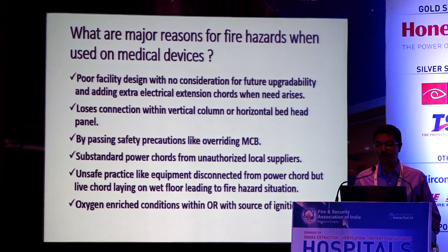The horizontal bedhead panels and vertical columns need to be maintained also. But people don't care for those things, although they are being used heavily. So we need to have a maintenance schedule for those things. Bypassing the safety precautions, like overriding the MCBs, is something people try to do as a shortcut, which should be avoided at any cost.